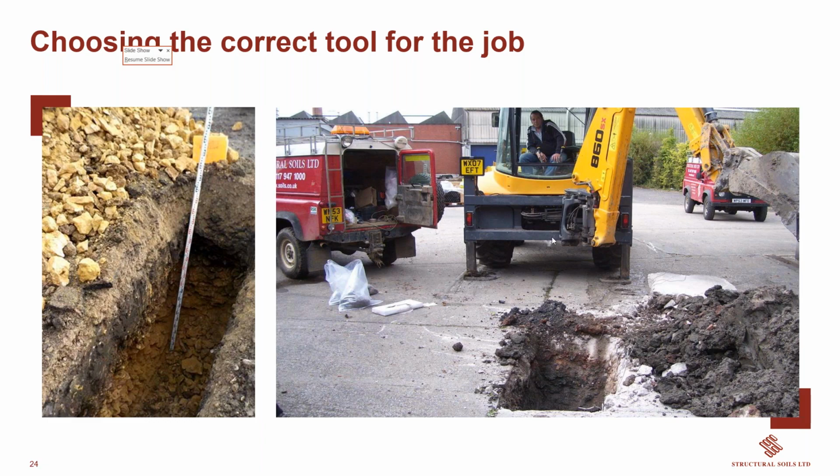If ever you're asked by your client to do some trial pits in a hard standing area, I would desperately try and get them to undertake window samples, where we need a much smaller hole, about half a meter by half a meter, and we can reinstate that very easily and effectively. If they are looking for larger samples, then we will do that in the soft ground areas to the right-hand side.